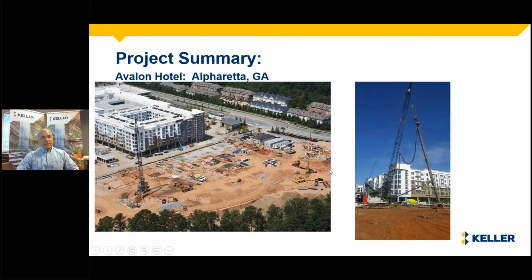Setup of a project as it's flowing. The nice thing, as we saw on previous slides, is that the system can be cleaner if enough excavators are being used to remove the spoils as you are drilling. That way, some areas can be released to the next trade. As the work progresses in this direction, the next trade can be mobilized and start putting the pile caps behind the rig.